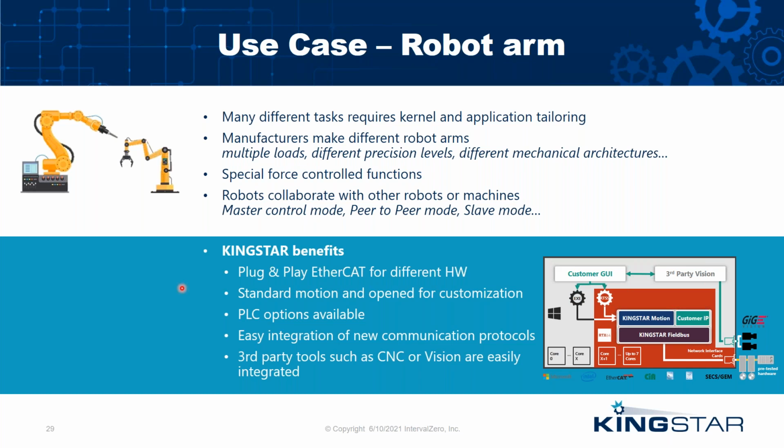So the interpolation and robotics control is still done by the robot controller. The robot can be taken and used on a different production line with a different mode later on. But there is no application, no program written in the robot for this CNC and robotic application. There is only one program, and it is written fully inside the CNC. This makes the development much simpler because the synchronization is automatically done inside this application.